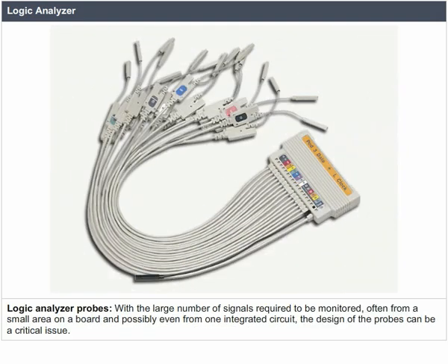Logic analyzer probes. With a large number of signals required to be monitored, often from a small area on a board and possibly even from one integrated circuit, the design of the probes can be a critical issue.